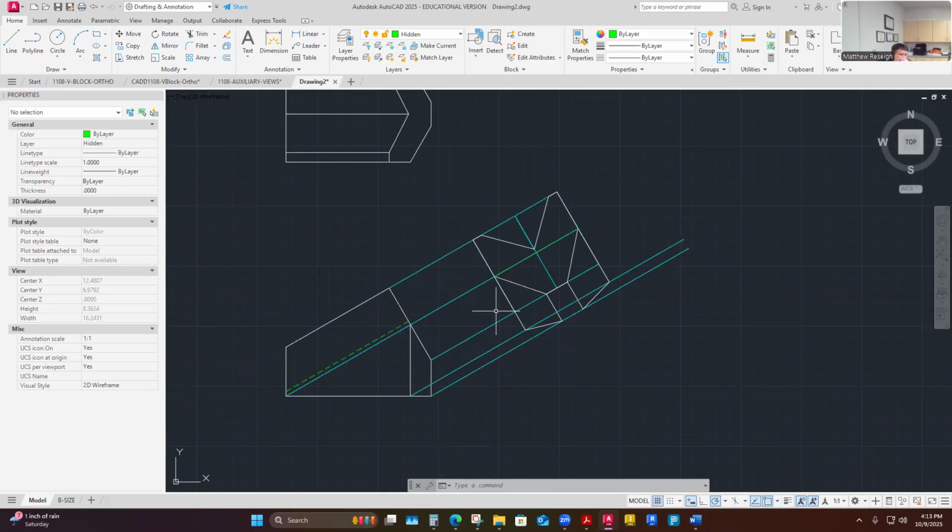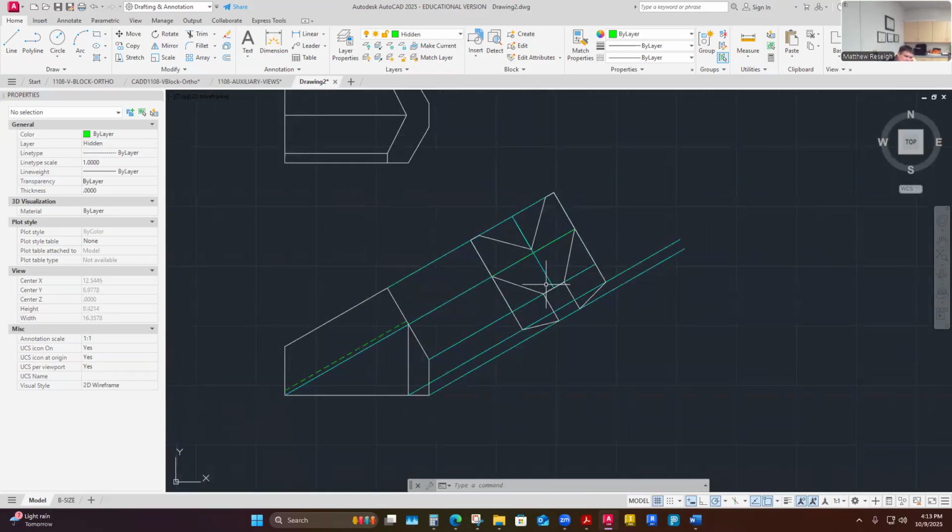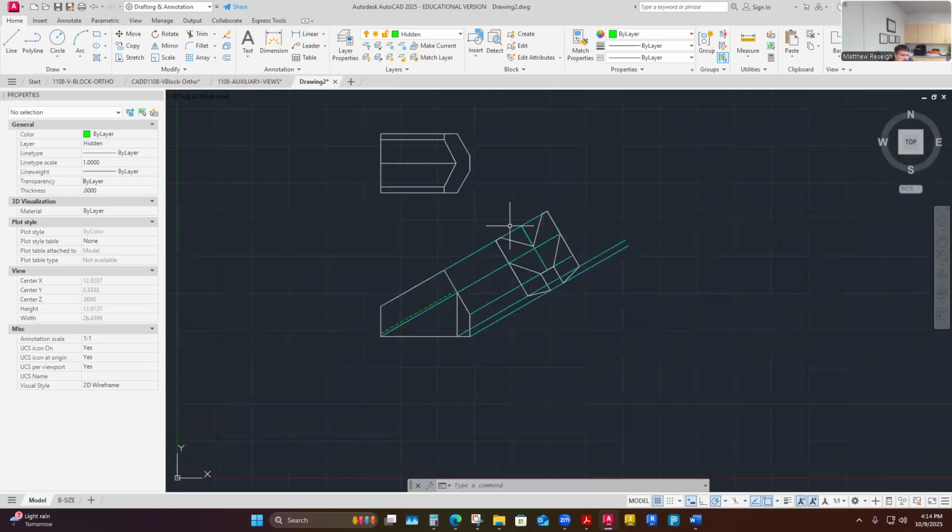So I'll think about the next auxiliary review, and I'll think about a couple different ways I can do it. Truly do it with the right spacing and projection lines, or rotate the UCS and do it, or just be careful like I did here. I haven't decided, but I'm going to continue this way. I think this one is done.